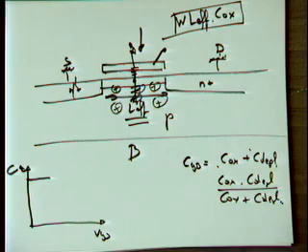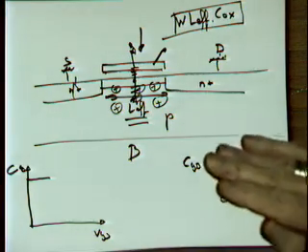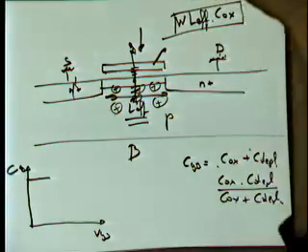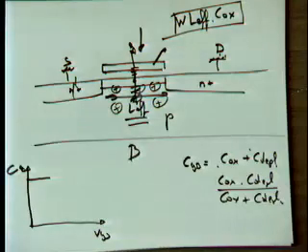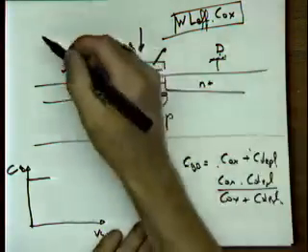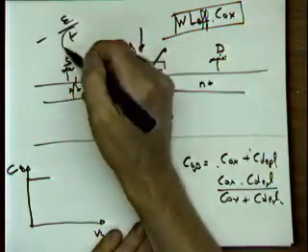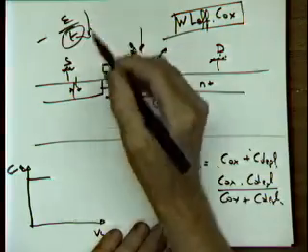Now the net effect of this is that it almost becomes like a wider and wider capacitance, and you remember that an insulation material that gets thicker and thicker gives a smaller capacitance, right? The capacitance is always proportional to epsilon over T. If T gets larger, the capacitance goes down.